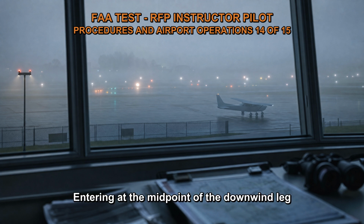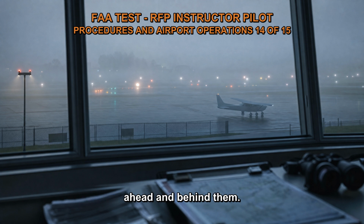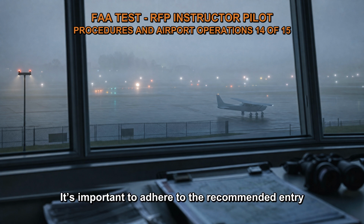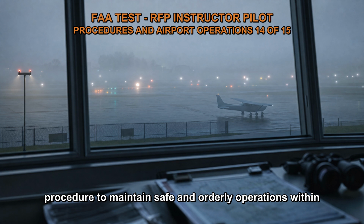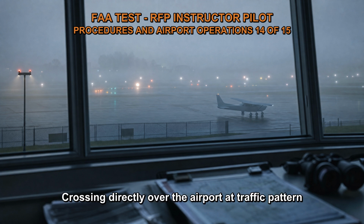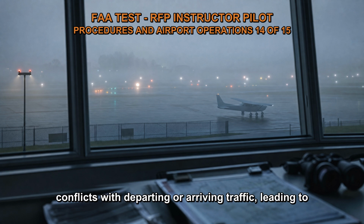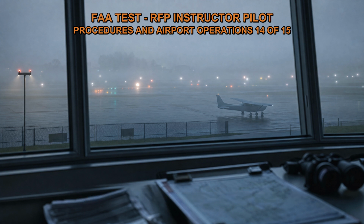Entering at the midpoint of the downwind leg ensures that pilots have a clear view of the runway and can effectively monitor the traffic ahead and behind them. It's important to adhere to the recommended entry procedure to maintain safe and orderly operations within the traffic pattern. Crossing directly over the airport at traffic pattern altitude and joining the downwind leg can create conflicts with departing or arriving traffic, leading to potential hazards.